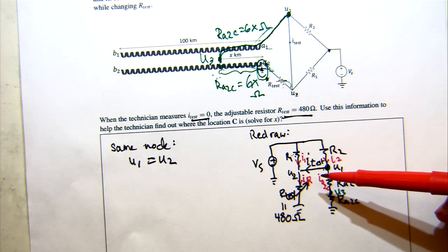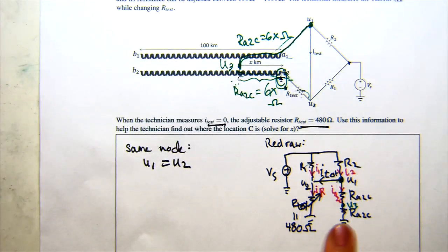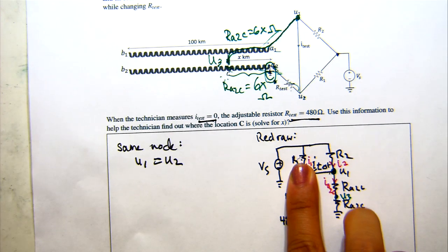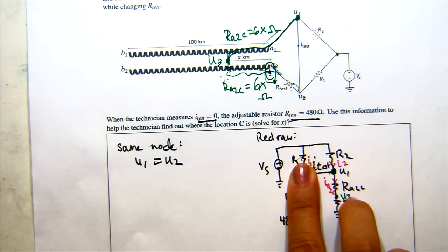What you could consider is the situation where you ignore half the node. Let's say I just consider the right side, right? Here I'd have 3 currents. I2 is coming in, I test is going out, and IA to C is going out, right? In that case, the sum of all 3 currents is going to be 0 as well by KCL. In that case, I test is only 0 if I2 equals IA to C. But that's not always true, right? It also depends on other things.